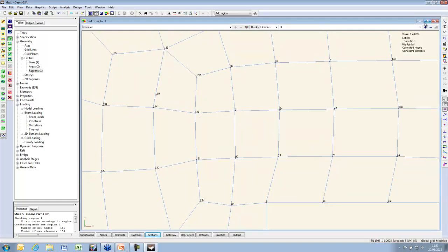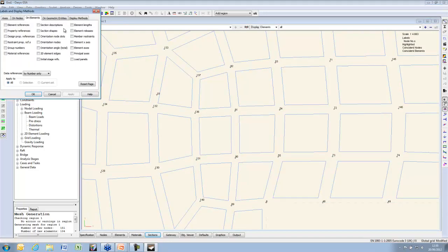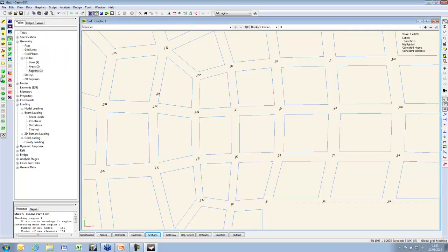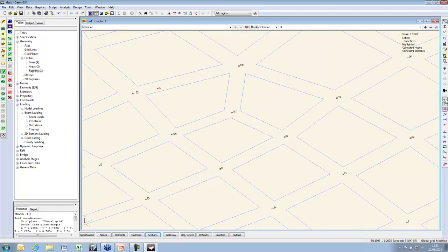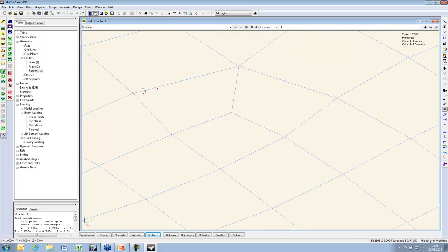we can see that that node is on the surface, but if I switch on tied interfaces, just rotate about that point. It's actually node display off mode. You can make out little red crosses associated with that element. So this node is now fixed onto the surface, and so you can apply a point load onto the mesh, and it's then distributed onto the 2D element accordingly.